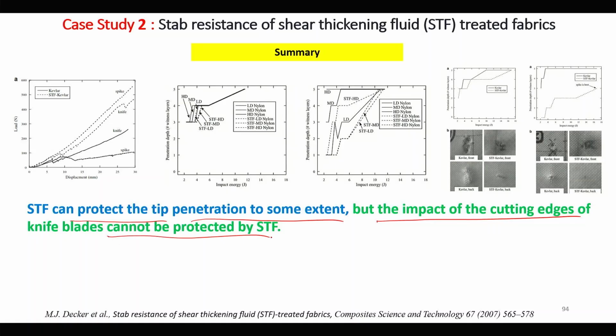So, for improving the cut strength, the STF does not work, but for tip penetration where high energy, high speed, high shear rate is there, in that case STF will work, because in knife penetration along with the cutting is there.